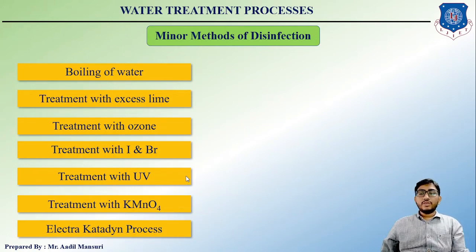So sterilization with ultraviolet rays does not impart any additional taste or odor to the water as no chemicals are added, but it is very costly, right? And needs technical knowledge and carries the possibility of interruption due to failure of electricity. So this method is unsuitable for treating large scale public supplies.